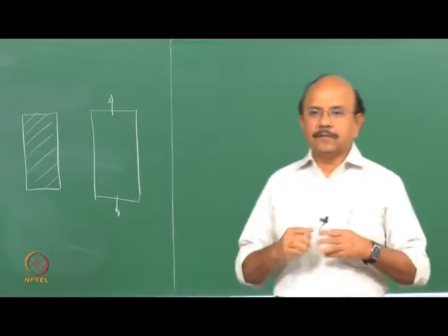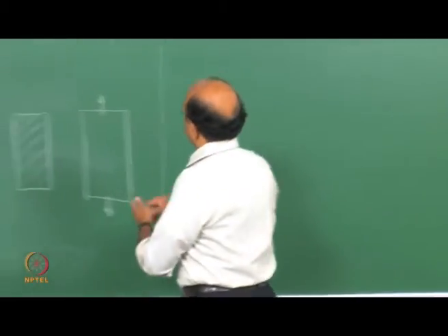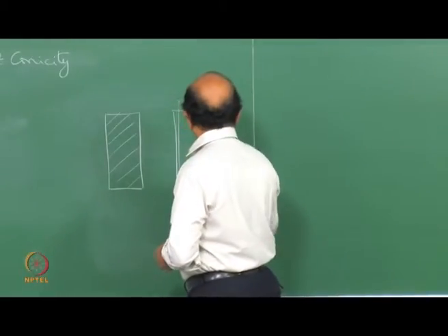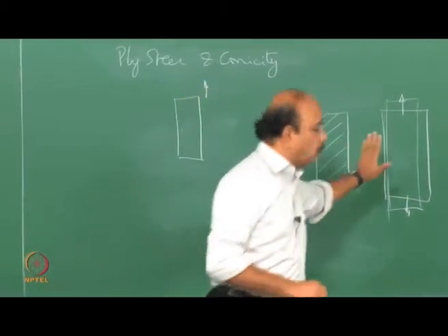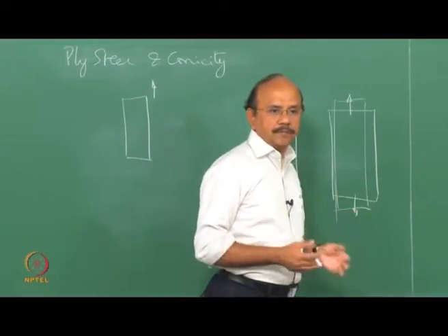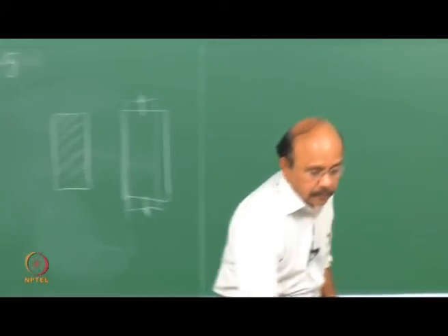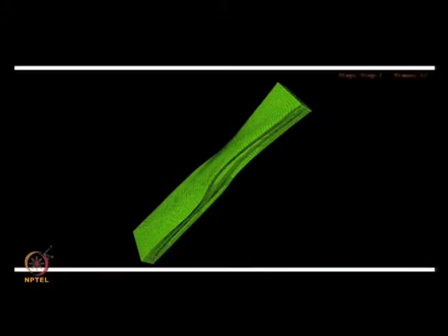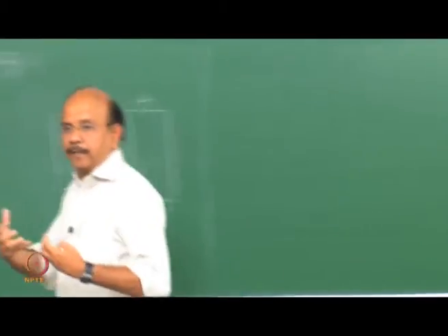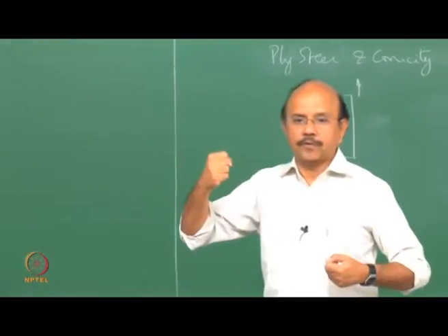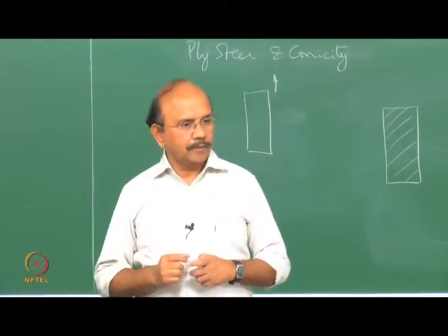If it were steel, I know what you would expect. It would just go like that, and this will be in one plane. There won't be any out-of-plane deformations. All right? Now let's see what happens here. You pull it. Oh wow, I didn't apply any force in the other direction. I just pulled it, and what happened? The whole thing twisted. So in other words, there's a coupling between this longitudinal force, or one force, and the other moment and so on.